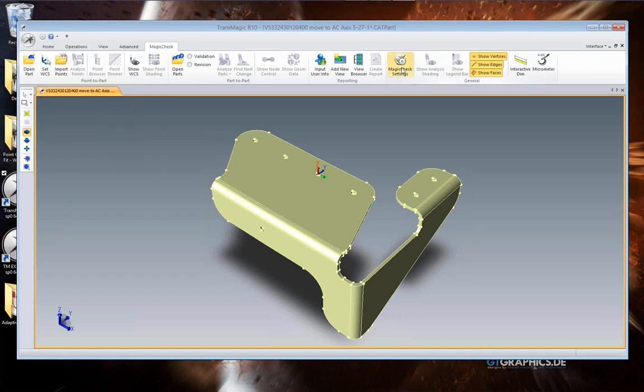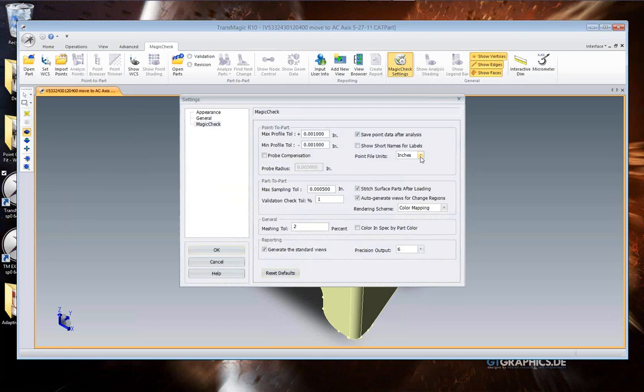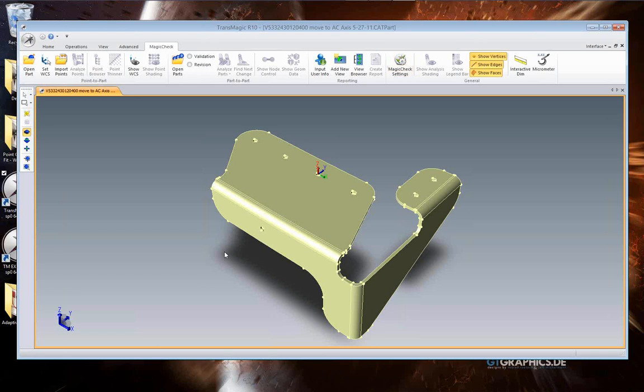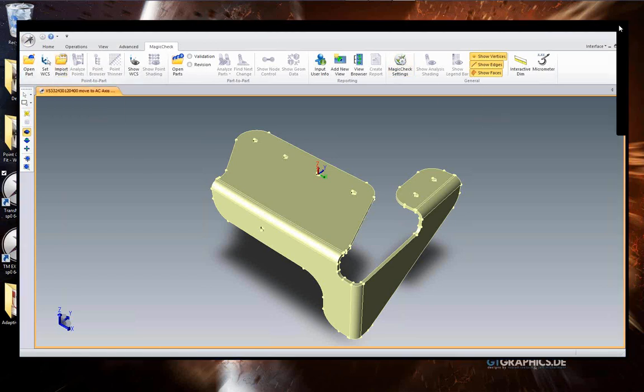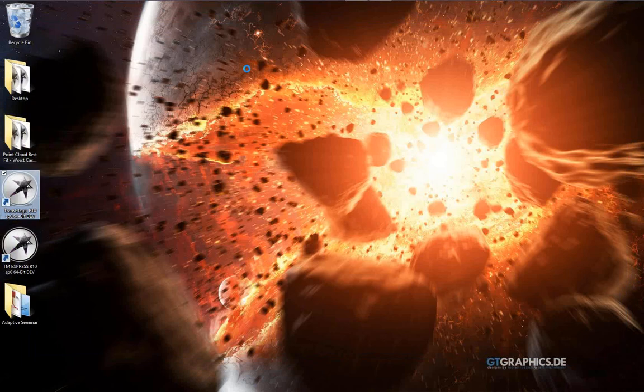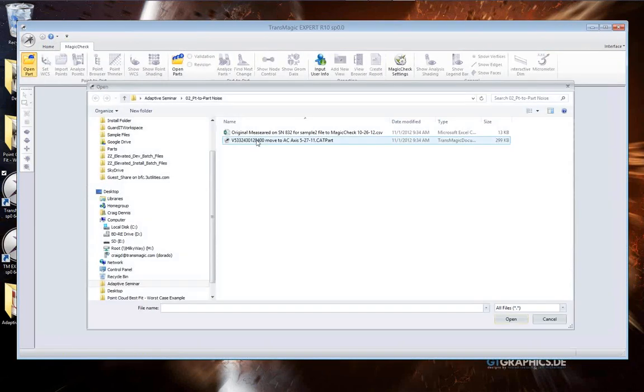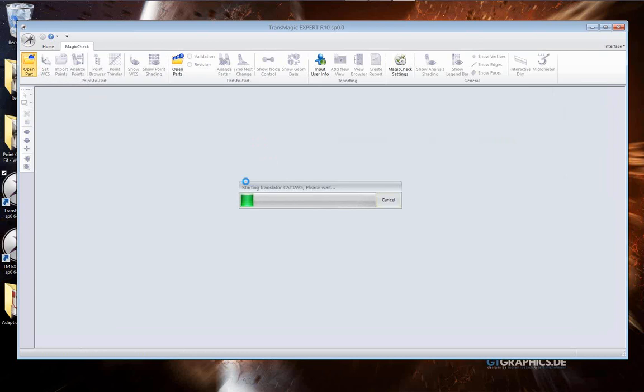And I noticed that they've come in at 0.039, which is my reminder that the point set was measured in millimeters. So let's go over to our settings here, change our point import to millimeters. If this is included in the point file, we'll automatically set this, but most point files do not include the units of measure that they came in at. So let's import our points. Oops, I'm sorry. I meant to expand that one more time.